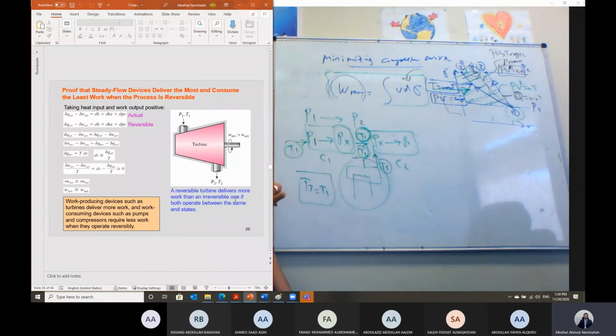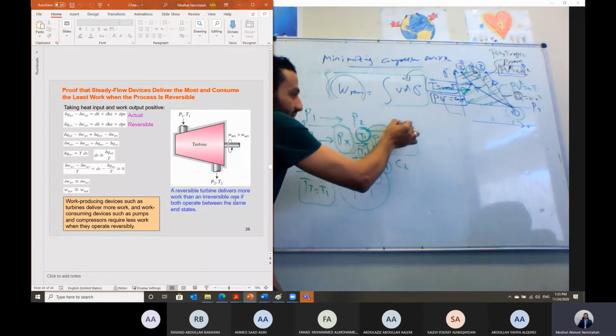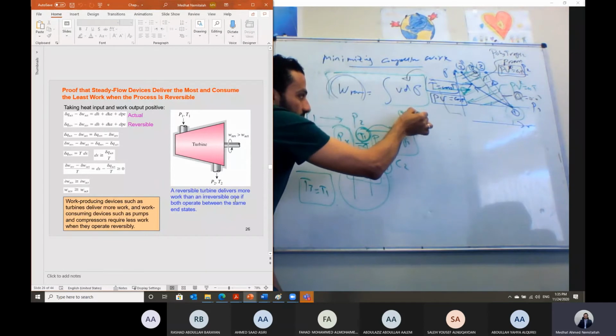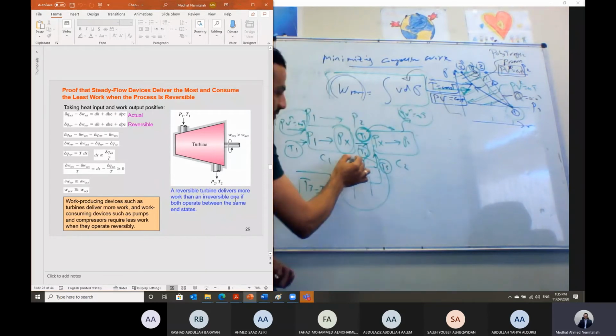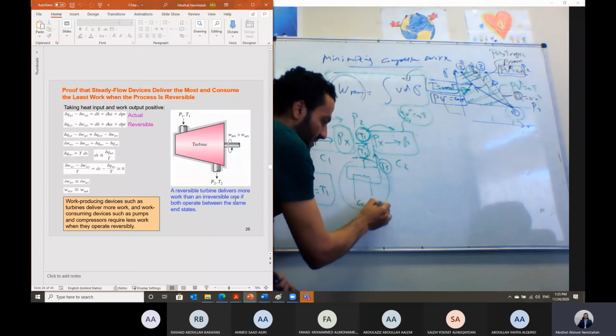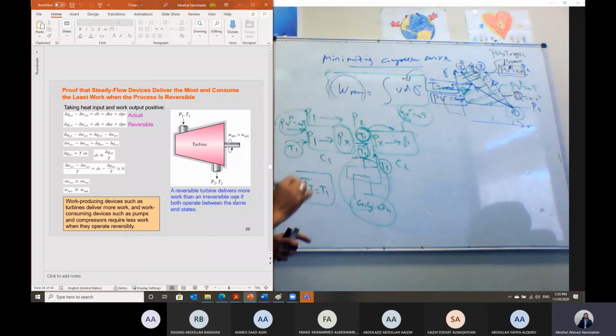Then I can compress in the second compressor. The process here is polytropic, PV to the power n is constant, and in the second compressor it is also polytropic, PV to the power n is constant. But in between, we have cooling water, a cooling system, as the gas leaves the first compressor, the first stage.